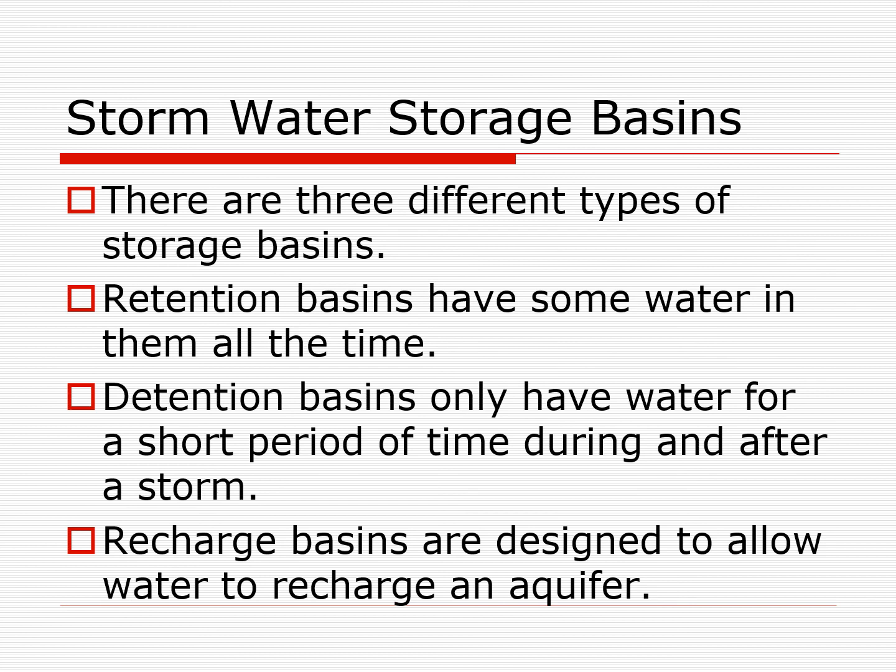So there are 3 different types of storage basins. There is a retention basin, and that has some water in it all the time. A detention basin only has water for a short period of time during and after a storm. And a recharge basin is designed to allow water to recharge an aquifer.